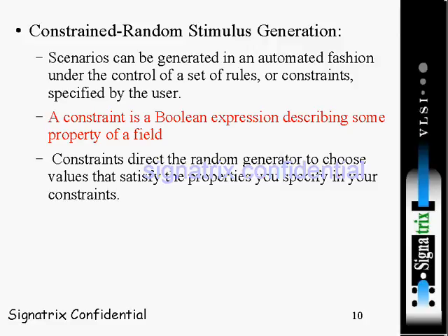Suppose I want to force the input vectors to those 10 masters. I am going to tap that grant signal from all the masters, and I want to force the random test cases. We know that at a time only one master will get the access, I mean the grant signal will be high. So in what way should I generate the test cases? Suppose we are having 4 masters.